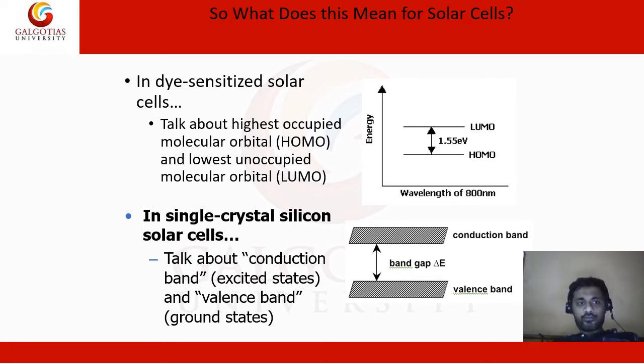It is a form of photoelectric cell, defined as a device whose electrical characteristics, such as current, voltage, or resistance, vary when exposed to light. Individual solar cell devices are often the electrical building blocks of photovoltaic modules, known colloquially as solar panels. The common single junction silicon solar cells can produce a maximum open circuit voltage of approximately 0.5 to 0.6 volts. Solar cells are described as being photovoltaic irrespective of whether the source is sunlight or an artificial light.